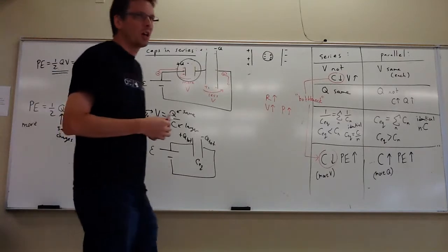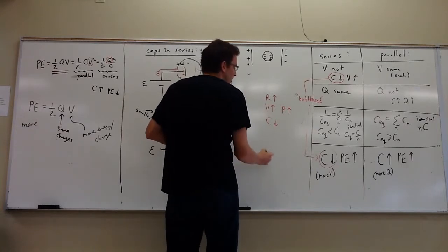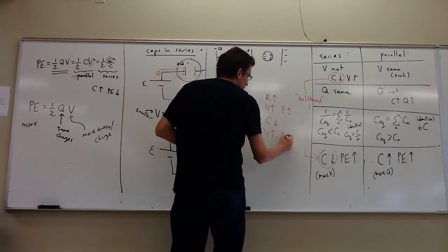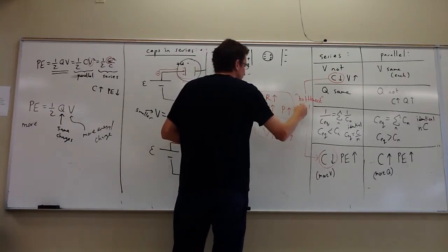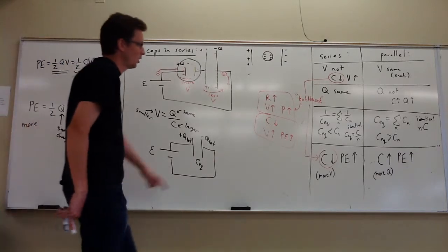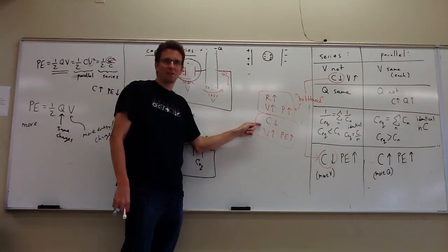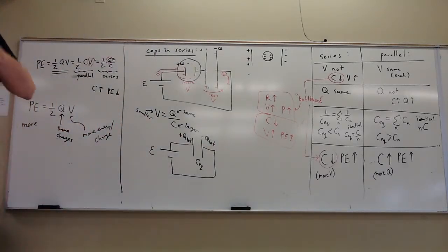Now we have that the small capacitor is acting the same way, right? That's the bottleneck. The small capacitor in here is going to get the larger voltage drop and the most energy stored. Okay? That's the bottleneck idea, right? That's where all the action is. In a series circuit, the big thing in the chain, the thing that is the biggest annoyance, is going to get the most attention. The large resistors and the small capacitors, right? The small capacitors are more difficult to charge, right? They're more difficult to contend with, just like large resistors, right?